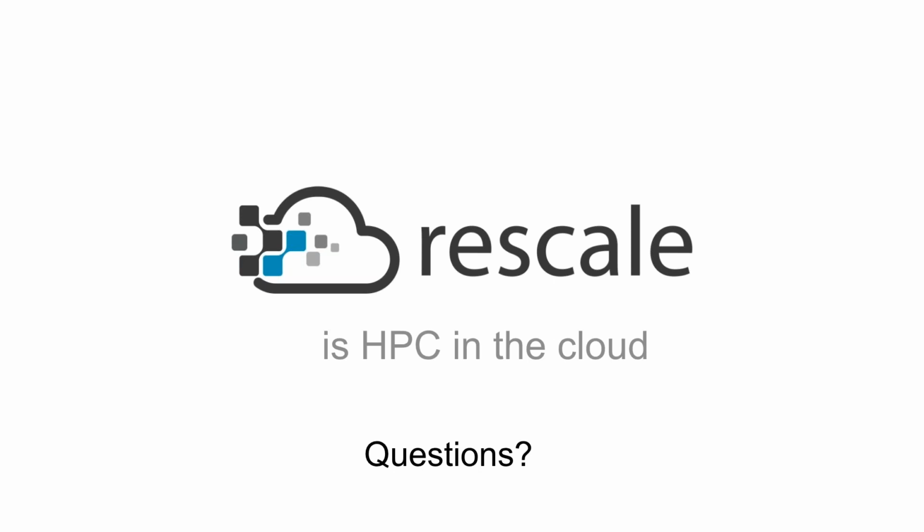Thank you, Bernardo. It looks like this question is for Cooper. This is from Sarah. Is the meshing in Converge really fully automated? Yeah, thanks. That's a great question. This is one we get a lot, especially from new users of Converge. Yes, the meshing in Converge is fully automatic. It's one of our biggest selling points. The only thing the user needs to do with respect to the meshing is provide a clean, watertight surface file that represents the model you're trying to simulate. I can also say that with Converge 3.0 and newer versions, they're going to be coming out next year.